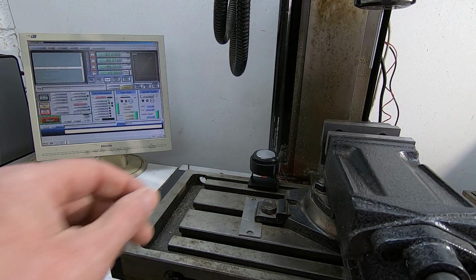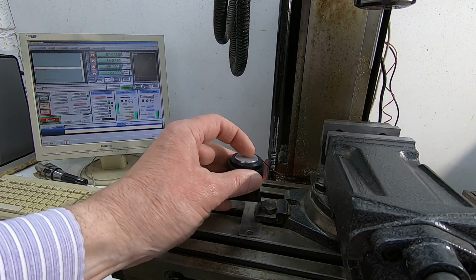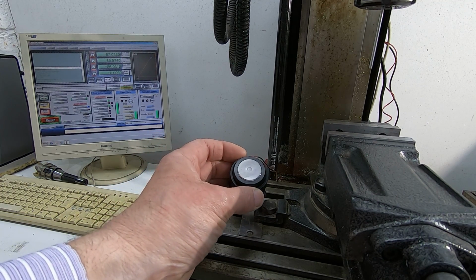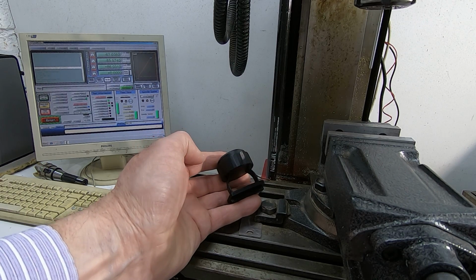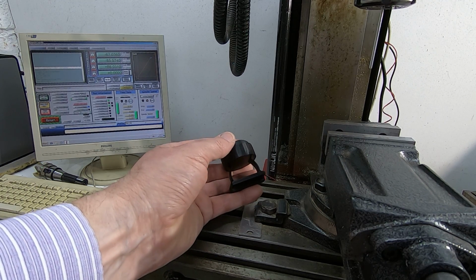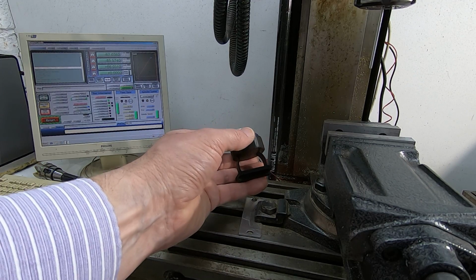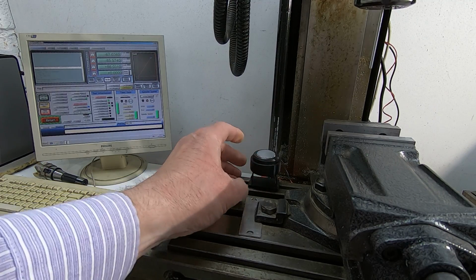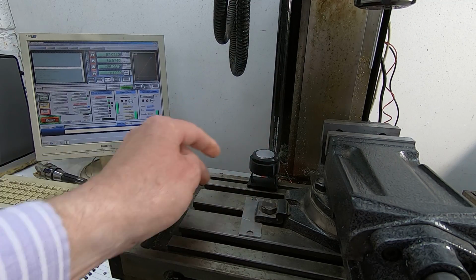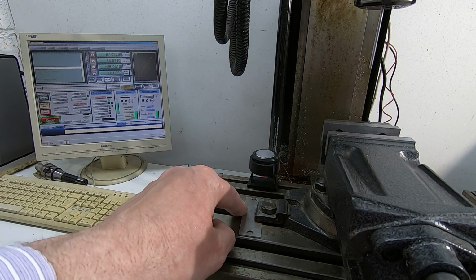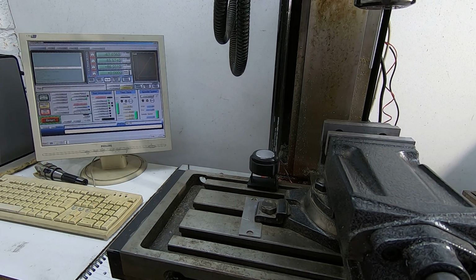Now the way I have these arranged is it's just a simple metal pad, and I've modified this mill to allow me to connect various probe types, but this just goes to the probe input, and it's on a 3D printed little frame here. And if you're wondering what this is for and why it looks so flimsy, it's intentionally designed so that if for any reason, for example, I forget to plug the probe wire in and the tool comes down, it will basically smash the bottom off this and flatten it rather than breaking the tool. And these are sacrificial. I haven't actually broken one yet, but it's only a matter of time.